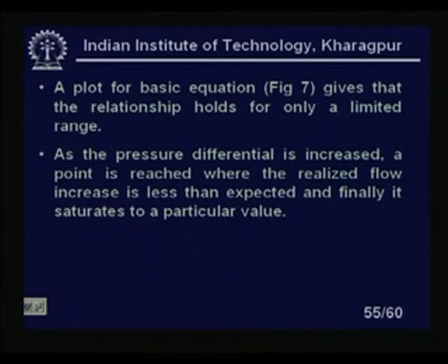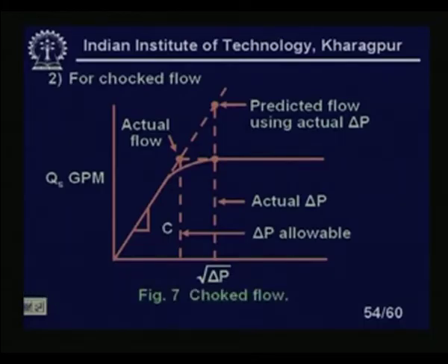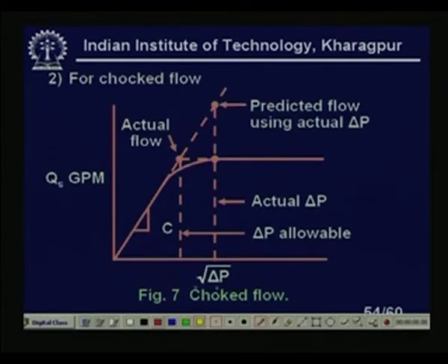and finally it saturates to a particular value. Unlike the stem movement, if you make a change of stem, do not confuse it with the stem movement. On the X axis we are plotting delta P, the differential pressure. We are increasing the differential pressure in this direction.